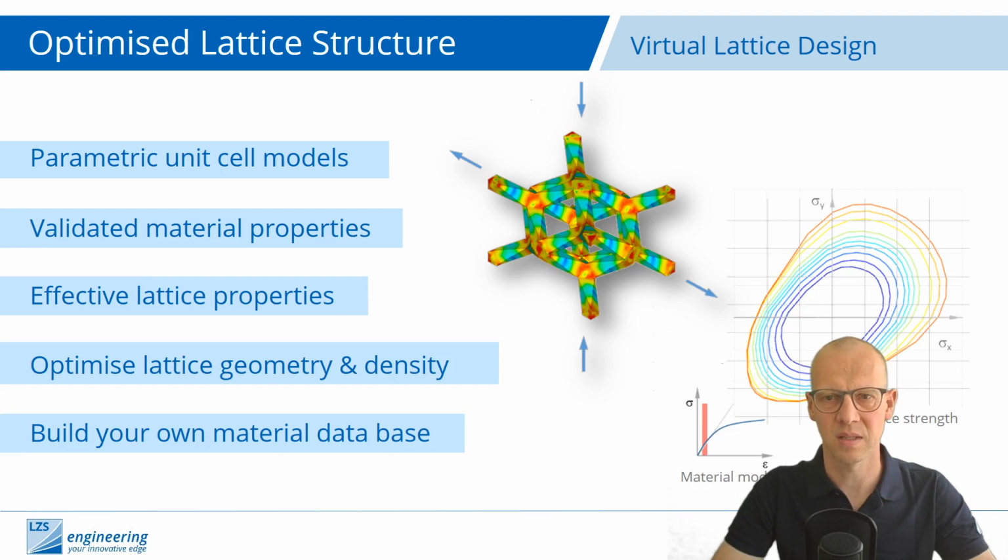And the first thing a simulation guy always does is to design a parametric unit cell model. So this means we modeled such a unit cell for a lattice cube, and because it's so small and it has not many design features, you can modify it quite easily and can test a lot of different geometries and can model easily quite strange grid densities, grid structures, grid components.